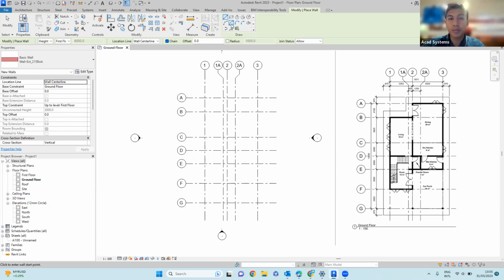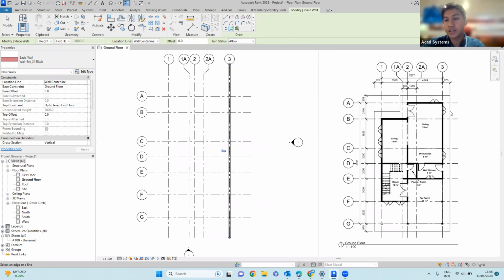And then for the drawing method, I will take these pick lines. There's a cursor there with a green line. That command is pick line. So just click here, and then you can just pick lines. In this case, we have grid lines, so we can pick these lines and the wall will be created here. Okay, so I will follow my reference here.